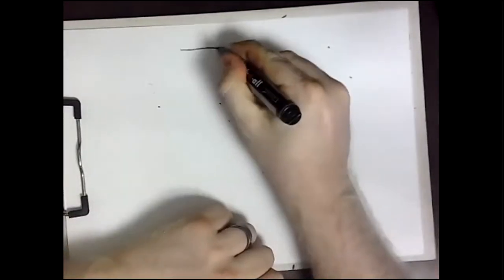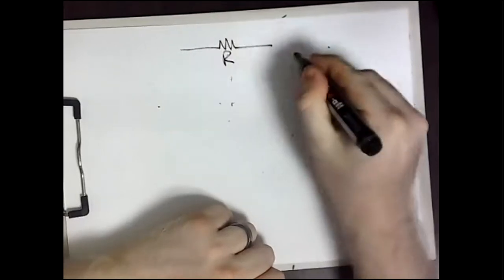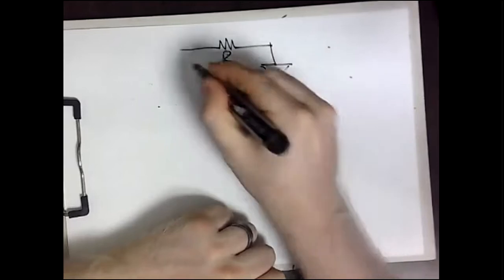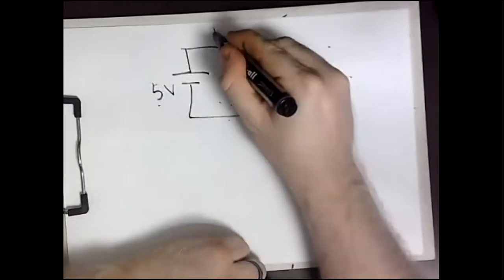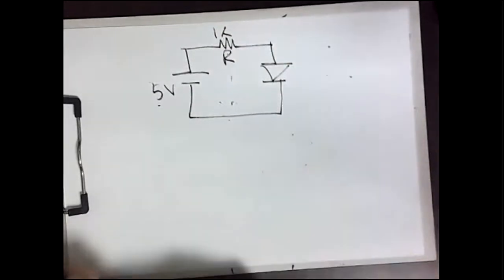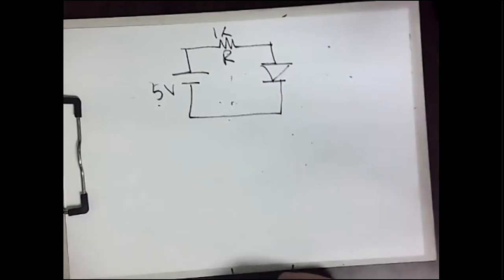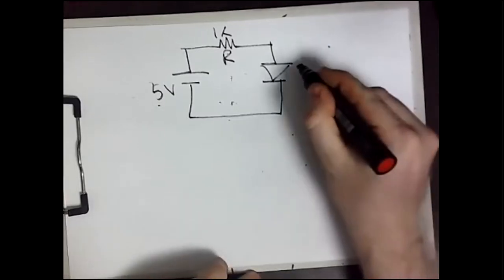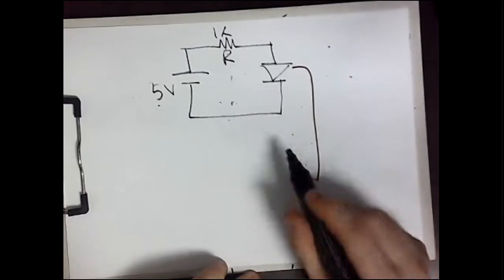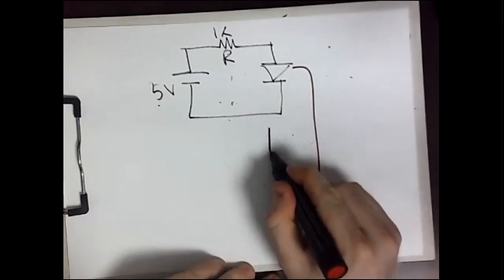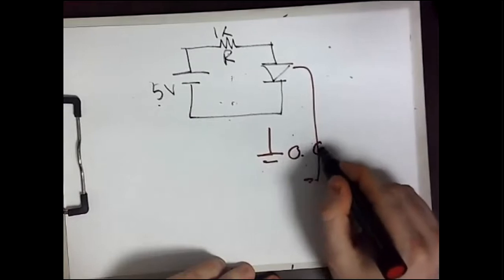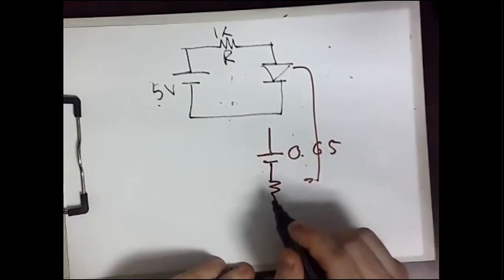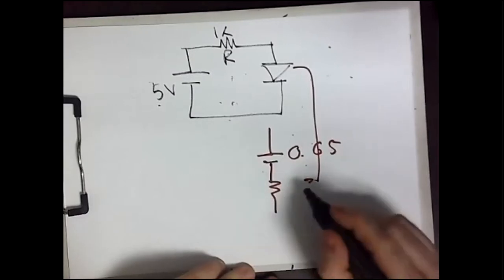Okay, so again, let's plot the same circuit, which is a resistance, a diode, and a voltage source. So this is 5 volt, this is 1k, and this is our unknown. Here we are assuming a piecewise linear model. In the piecewise linear model, you are going to replace this diode with a built-in potential, here given as 0.65, and a resistance, given as 20 ohm.